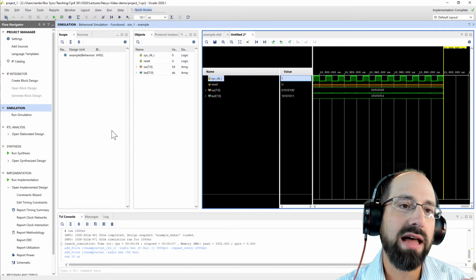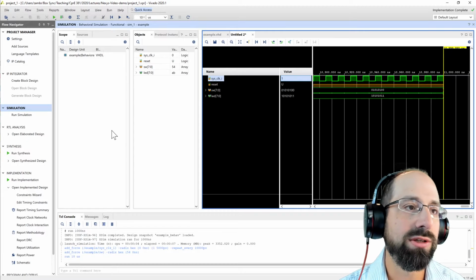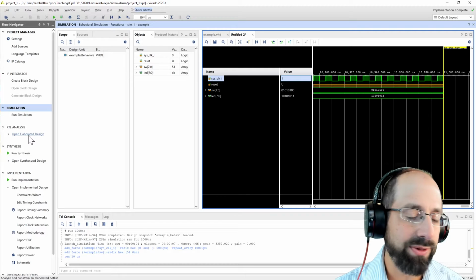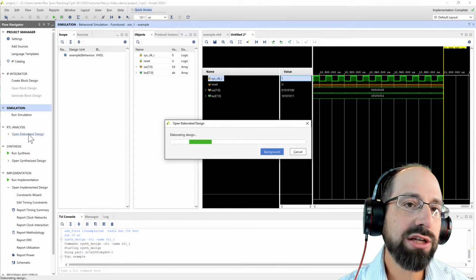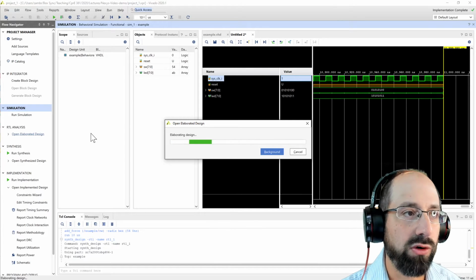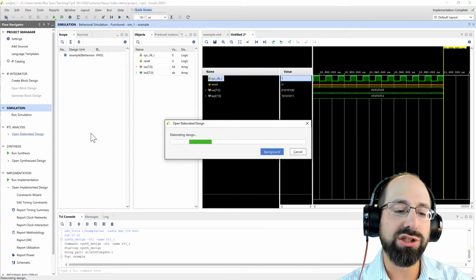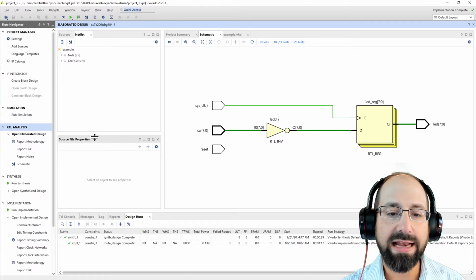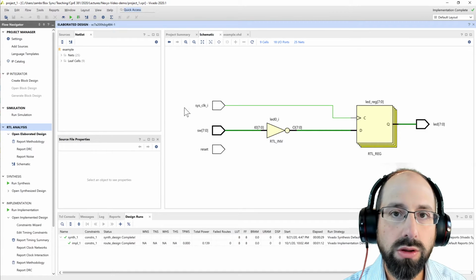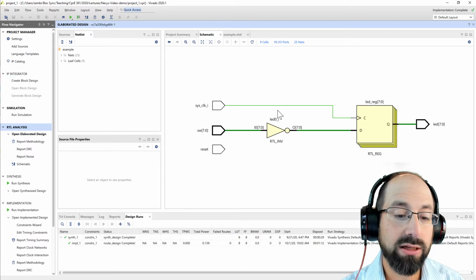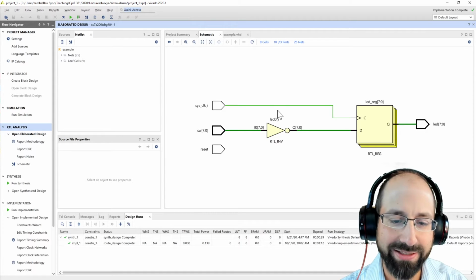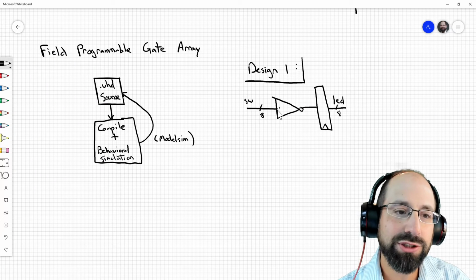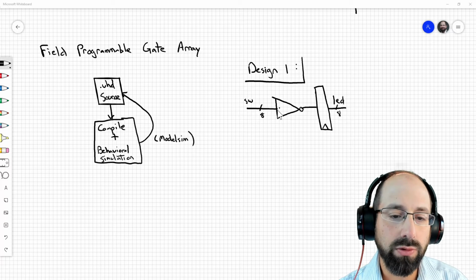The cool thing though is there's a lot more analysis that these tools have to do that we have to understand what to do. I'll get to synthesis in a second, but generally, ModelSim could provide this, but it just doesn't provide it in a way that I'm familiar with. It'll actually show you, if you click that feature for analysis of the RTL, what hardware it's generally trying to understand from your model. What is your behavioral model trying to do? And so this is kind of cool, I think anyway. And this should map pretty closely to what our diagram looked like. In fact, it really should be exactly the same as our diagram, right? So the design is what it is: input switch with an inverter getting mapped to a register.